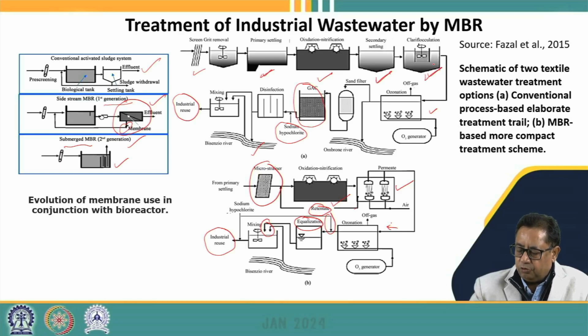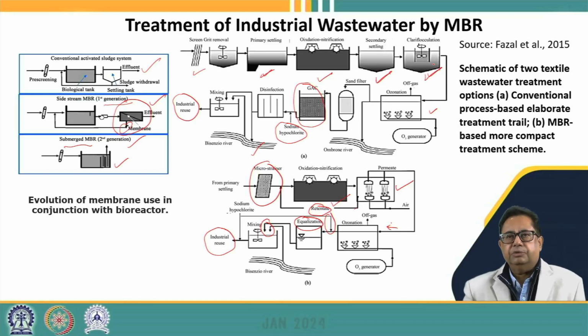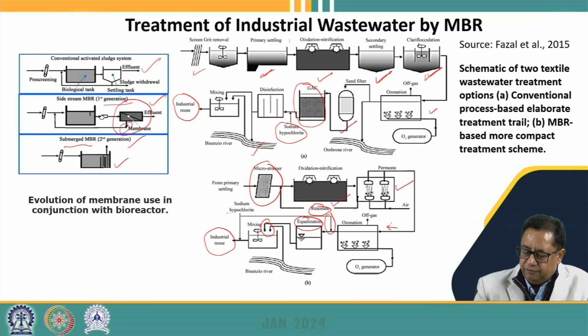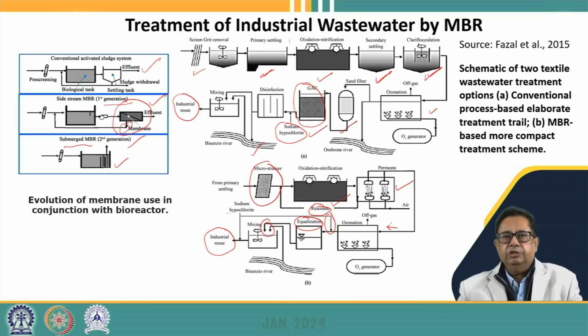tank and the clariflocculation, all these systems have been removed when we are using MBR in place of the conventional treatment systems. Similarly, we can see that the sand filter and the granular activated carbon, all these processes are removed during the treatment by using the membrane bioreactor.